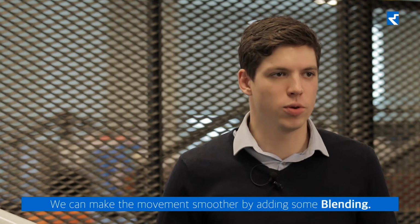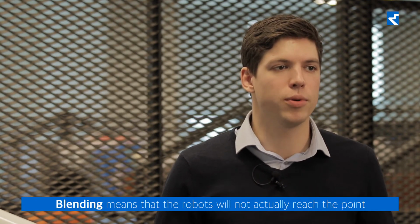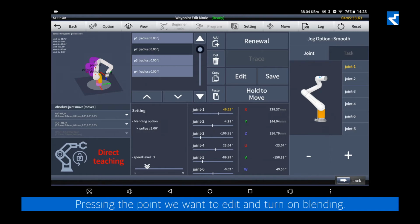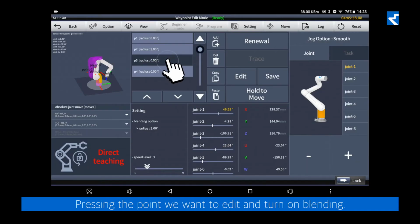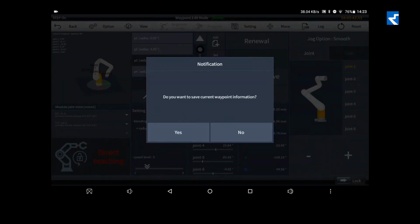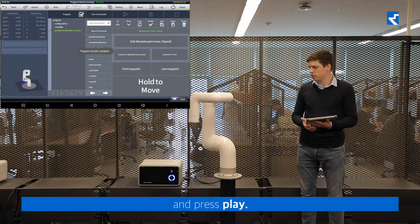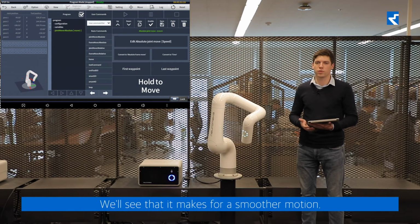We can make the movement smoother by adding some blending. Blending means that the robot will not actually reach the point, but kind of skim it. We can do this by editing the command again, pressing the point we want to edit and turn on blending. We'll do this for the middle points. Now if we save this, move to the first waypoint again and press play, you'll see that it makes for a smoother motion.